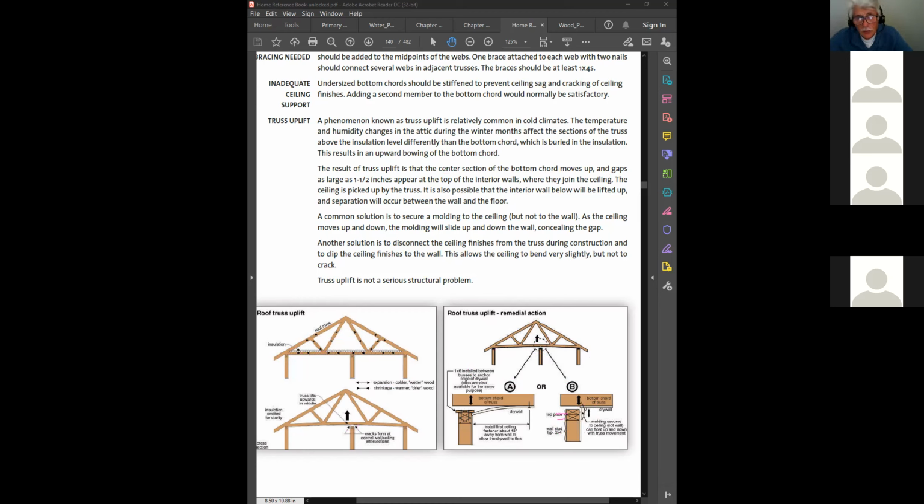So on average, when I have a bearing wall, and I have a top plate here, a top plate there, and a top plate there, like this is for one floor, well, most of the shrinkage occurs here because of the direction of the grain. This will on average shrink about 1/4 of an inch. So it's not too bad when you only have one story.